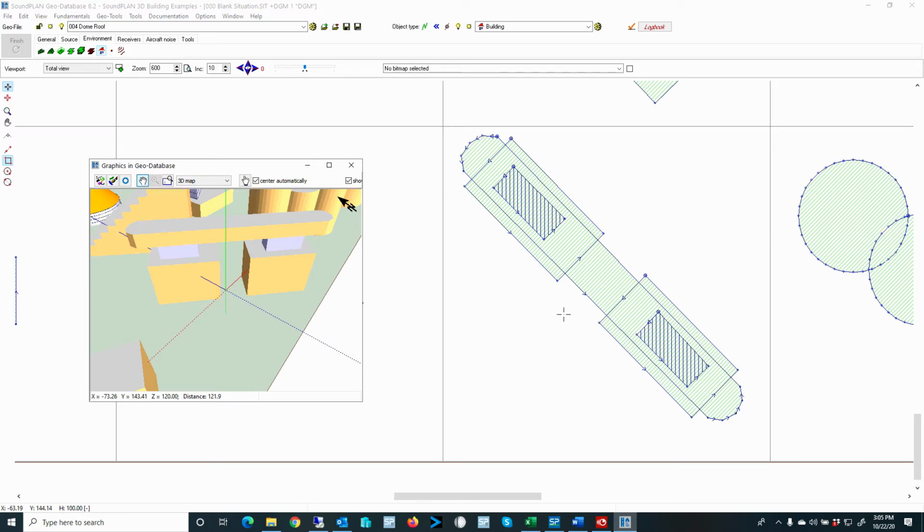Again, by overlapping and floating those buildings, of course, the sound can go underneath this big building at the very top. So it can go through this area if the line of sight is not broken. If the line of sight is broken, then of course the sound goes either over, under, or around the buildings.